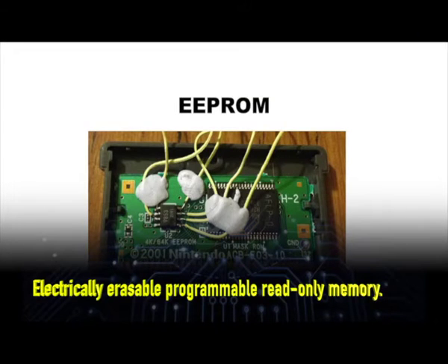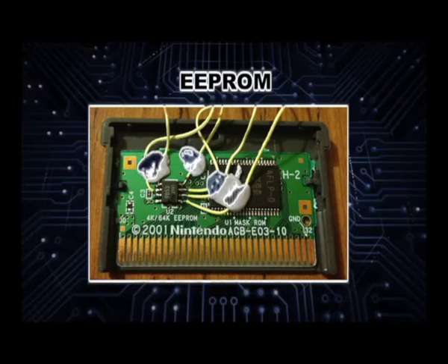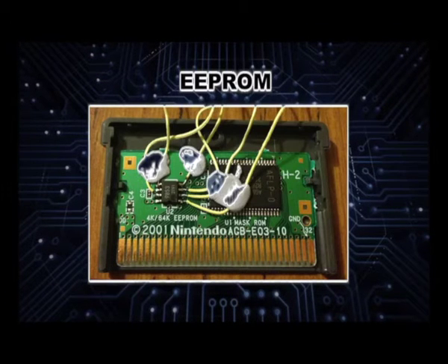Like PROM, you need a special device called a PROM programmer or PROM burner to write to and erase an EPROM. EEPROM, short form of electrically erasable programmable read only memory. A major drawback of EPROM is that the chip must be removed from the circuit for programming and that its entire contents are erased by ultraviolet rays. EEPROM is a special type of PROM